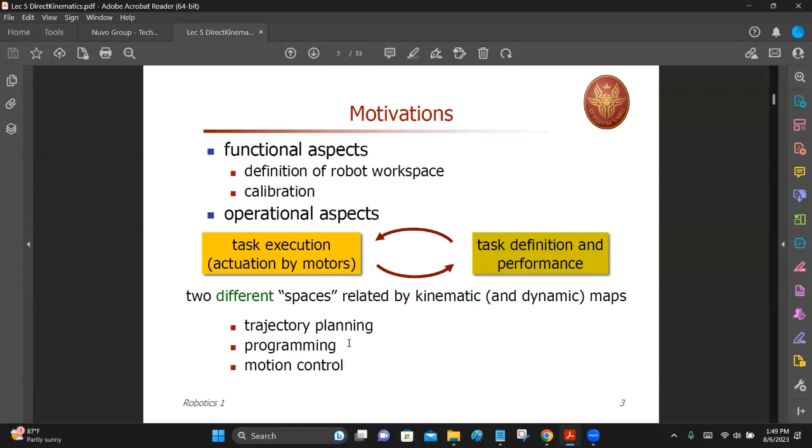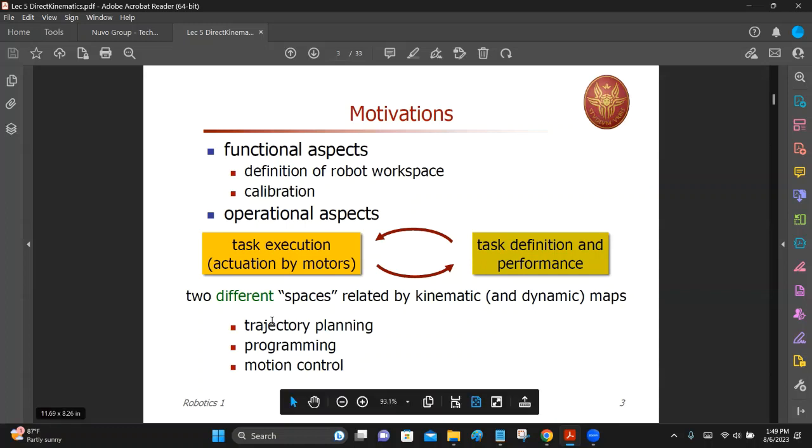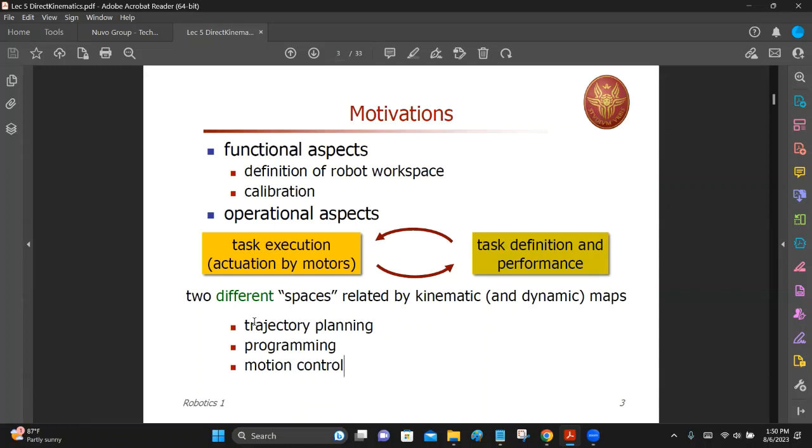Maybe 50 millisecond interval, and it uses a certain velocity, and based on the velocity, it calculates the position, probably taking 50 millisecond as the sampling interval. All right. So all these things are pretty straightforward things. You need to stack them on top of each other. So once you have the trajectory defined at a higher level, you can break it down into via points and samples of 50 millisecond interval.